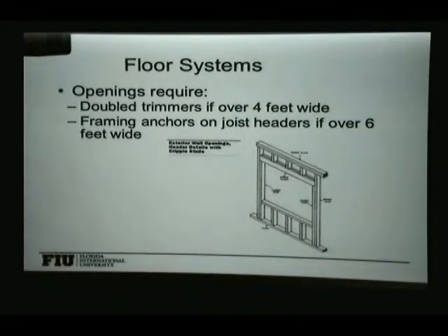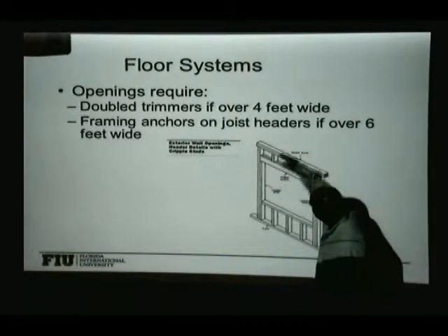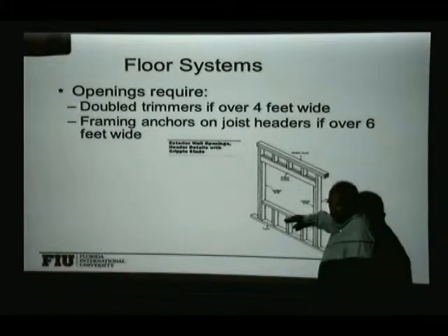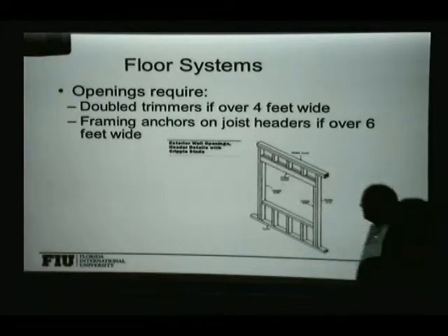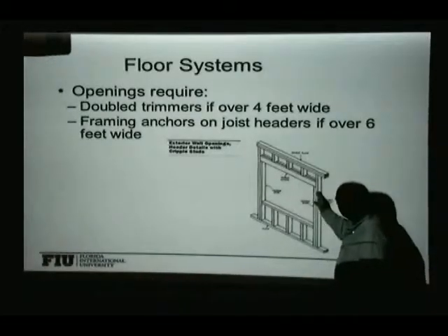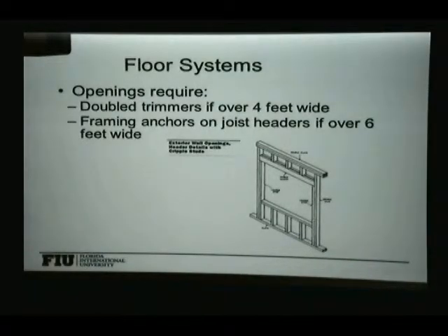Also, you may have to have openings in the wood structure. So if you have studs that are supporting the top and the bottom structure, and you need to make an opening, those studs get cut to the size. So you still need to count them because you need the whole material, even though it looks just a piece of it is required. And also you need to consider that at the edges of this opening, they're normally double support. So you need to have two studs on the end of the openings rather than the regular one stud. So those things you need to take into consideration.